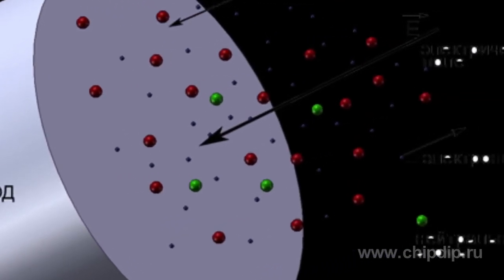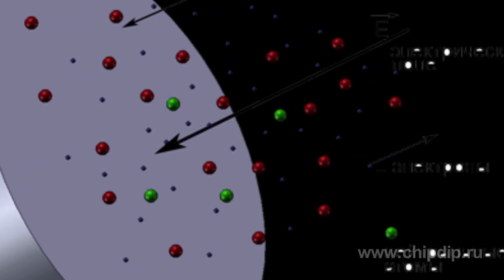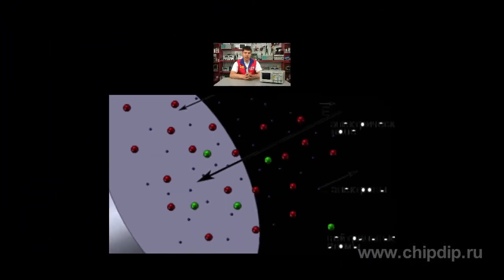The positive column has a good electrical conductivity because of a big concentration of electrons. Thus it has insignificant voltage drop. The positive column has both positive ions and electrons. Thus an intense ion recombination occurs here. This explains the glow of the positive column.